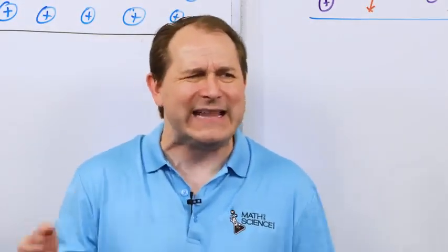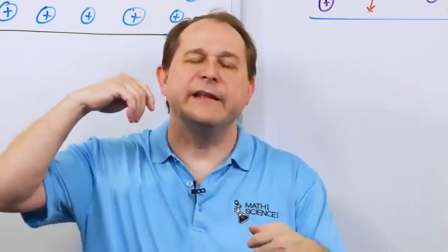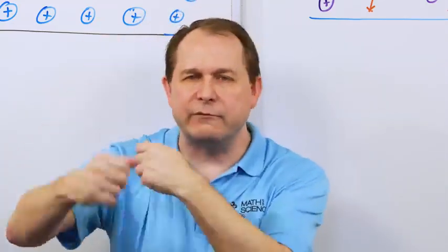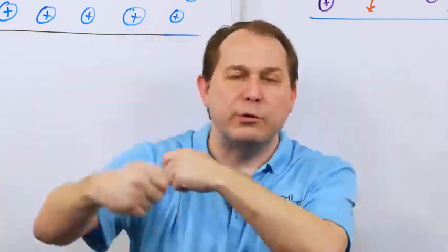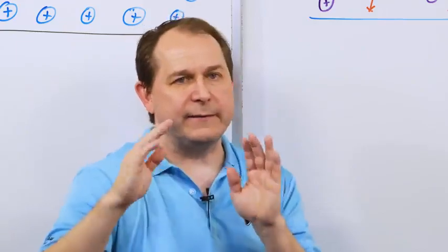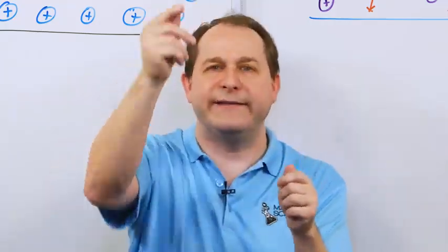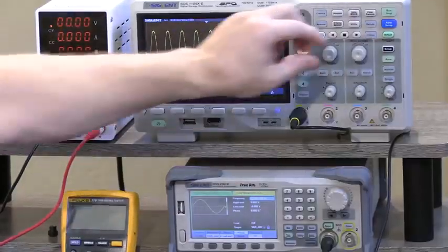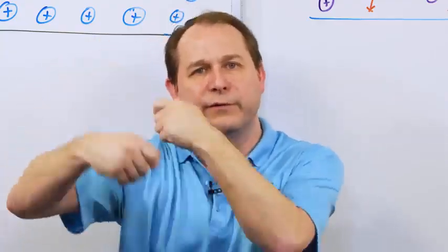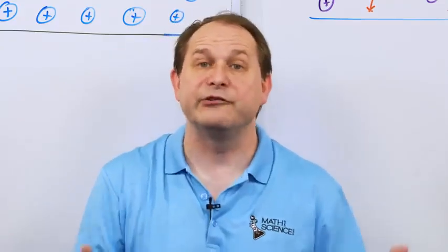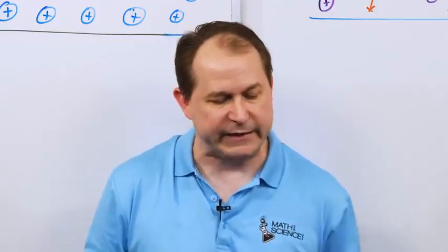Now you might say, why do they make it like that? Why does it have to alternate? Well, it's because of the way it's generated. I'll have a whole video on it, but it's all generated with rotating motor generators. Steam is flowing through a turbine and that's turning a generator, and the magnetic field is rotating in a circle. Half of the circle it's generating positive voltage and the other half it's generating negative voltage. As it turns around, it traces out this sine wave. This sine that we learn about in school is so important because when we use circular generators to generate a voltage and it's rotating, if you remember, the sine function comes from projections on a circle. That's why the shape of the voltage is a sine in the first place.